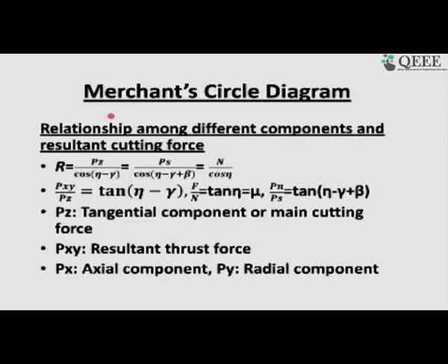He first gave a scientific treatment of the whole thing, how to put all this force together and correlate that, and that can be represented within a circle, and that is known as the merchant circle diagram, and the diameter of that circle actually becomes the resultant force R. So, let me try to draw this circle and we can keep on discussing this particular subject.